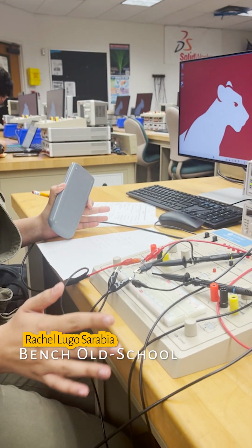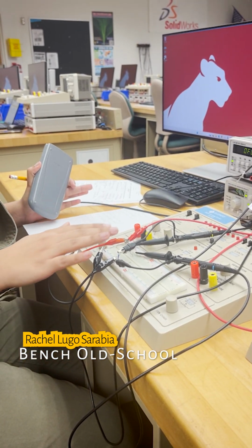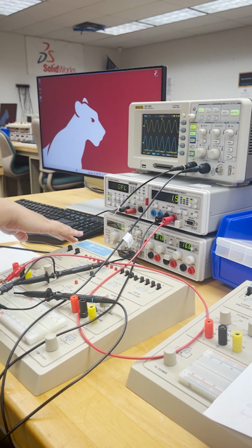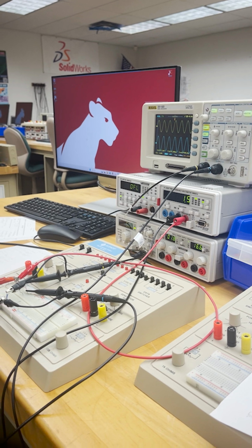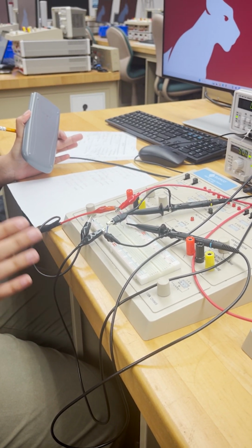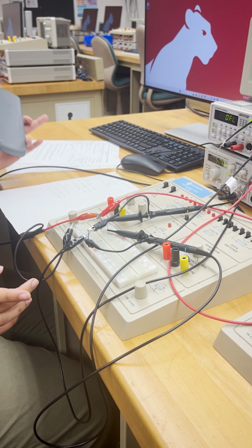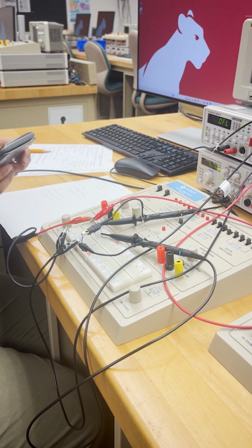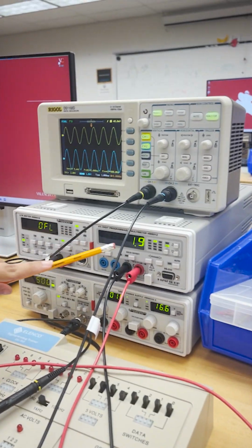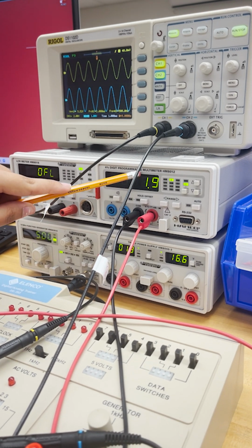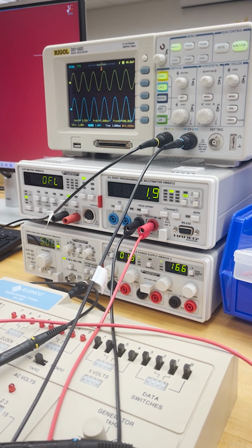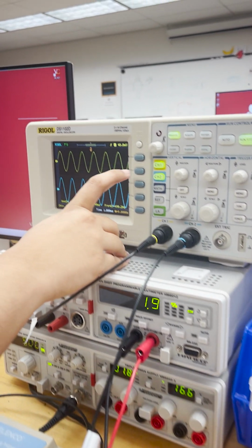After all our cables are set up, grounding all the cables and putting all our resistors and building our circuit and adjusting all the values in our DMM, our function generator, and turning on our oscilloscope, we're going to do the old school way of calculating VRMS, V peak to peak, and our time and frequencies. So in order to get our VRMS, we can actually see it here in the multimeter. It's the 1.9.